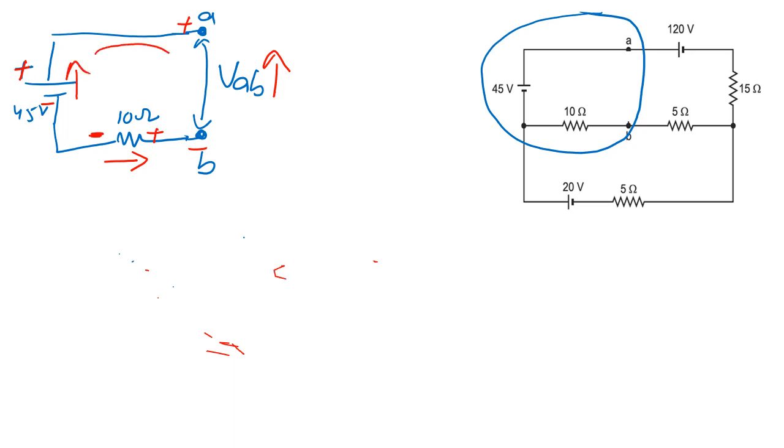So in this loop I want to apply the current. Here actually the I current is passing, but the I is the sum or the difference of the two currents. This is loop number 1. So in loop number 1, the current passing through the 10 ohm is I1 minus I2. So this current we have to take from the 10 ohm.